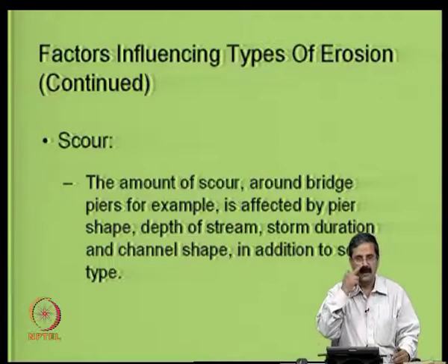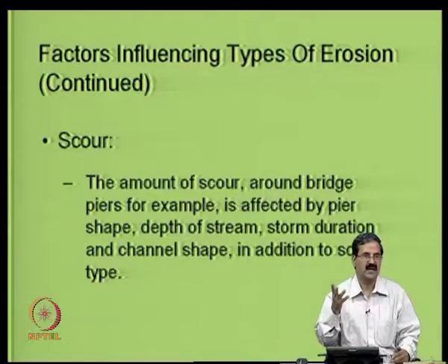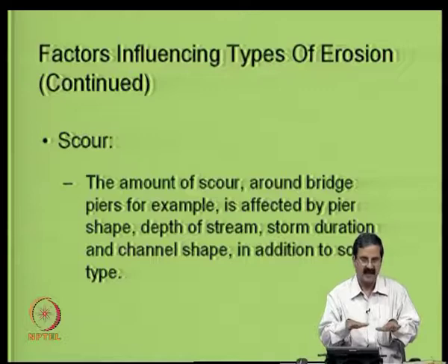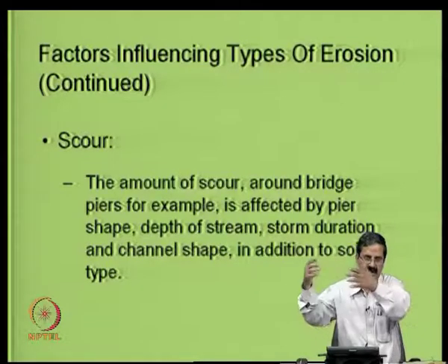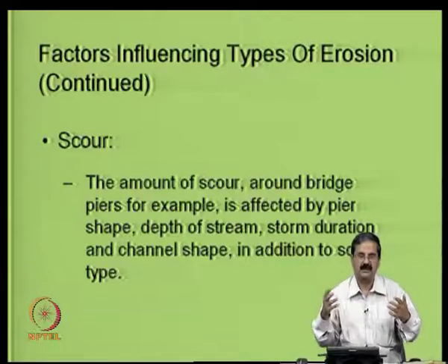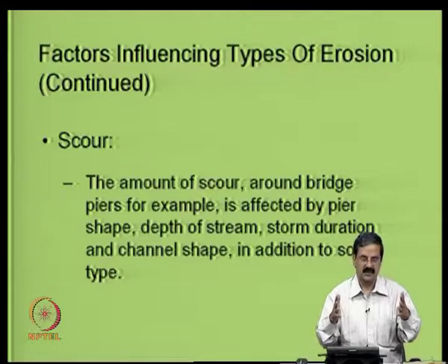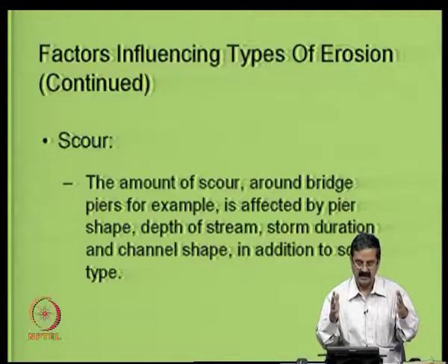Suppose in some cases the surcharge is not there, it is water: imagine the water level slowly rises and removes all that overburden next to the pier. What happens? The bearing capacity of the pier comes down, is it not?